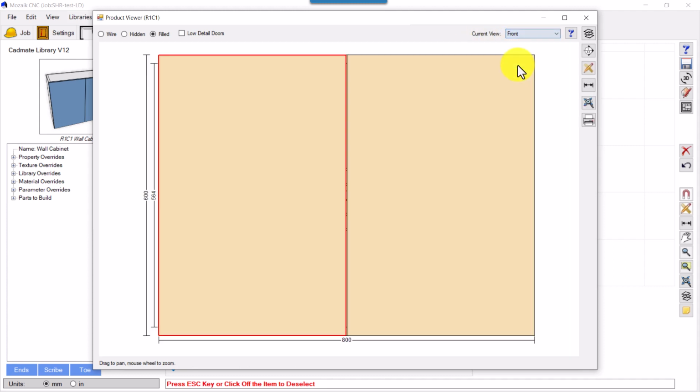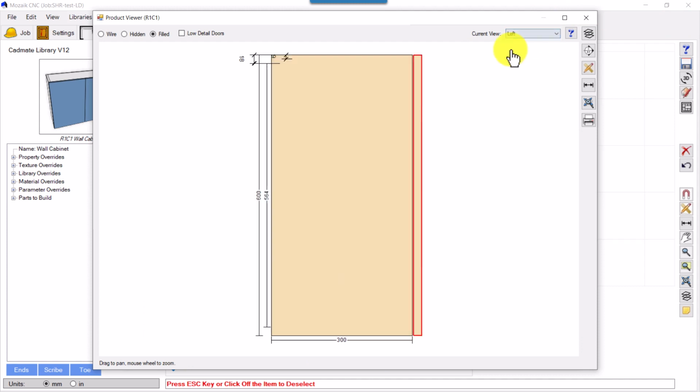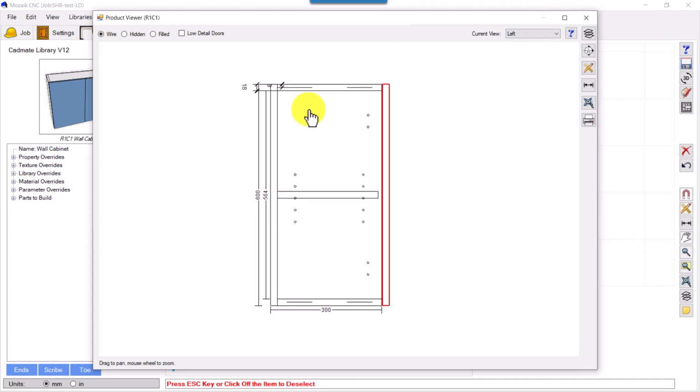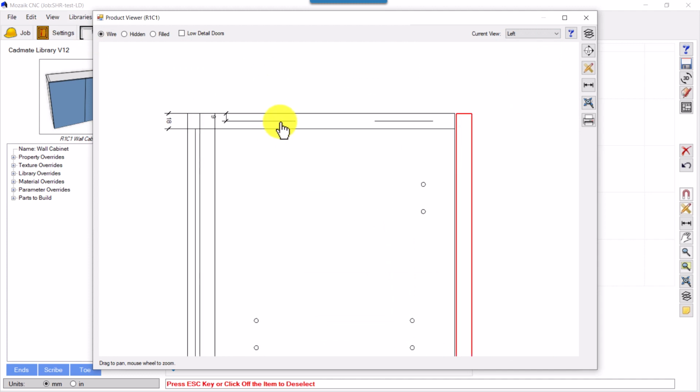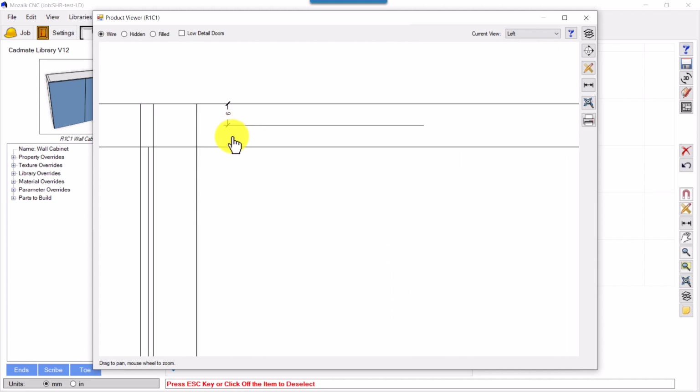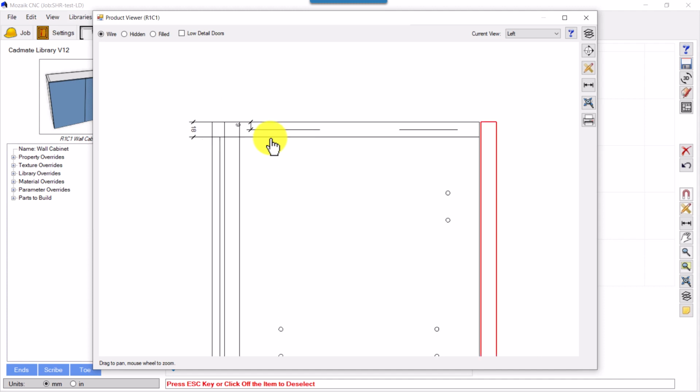Then in order to tackle that situation, what we do is we want these lock dowel route paths to be placed at 11 millimeter from the top, not 9, okay, a 2 mm offset.